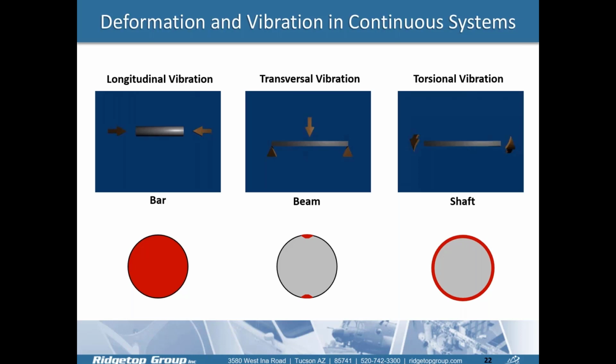So the next thing that we need to consider is which one of these vibrations are happening in the gear system, and we mount the accelerometer in the right place and in the right direction to collect this vibrational signal. Next slide, please.